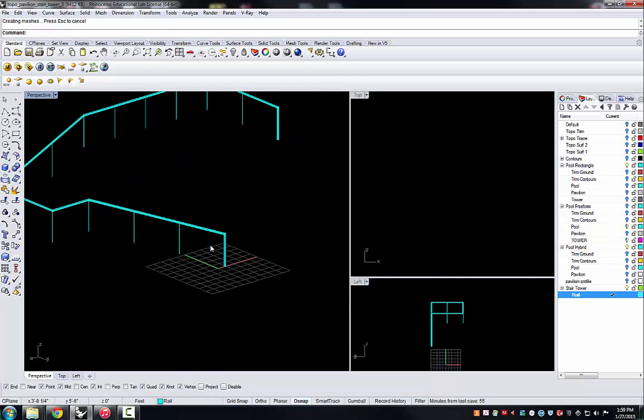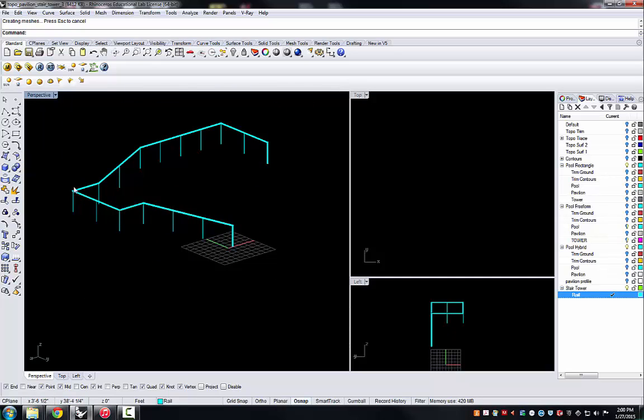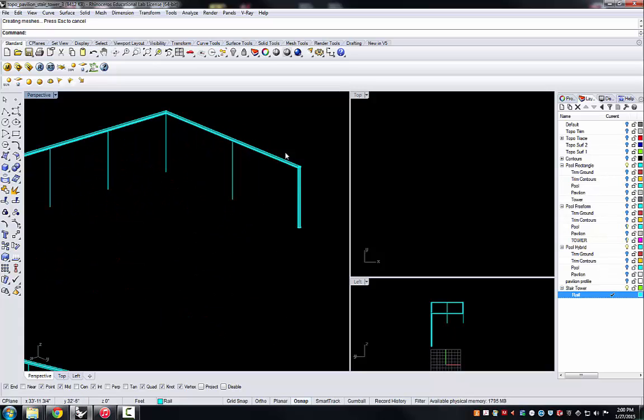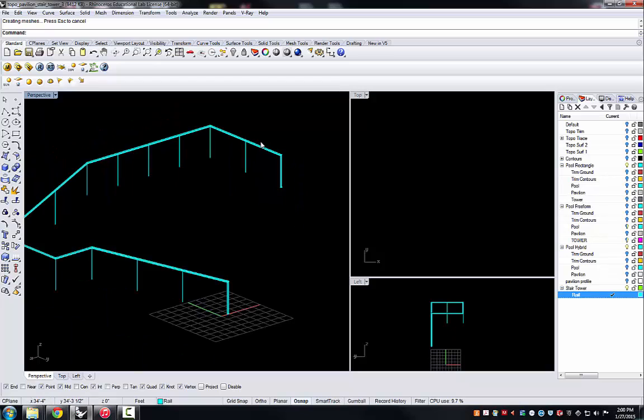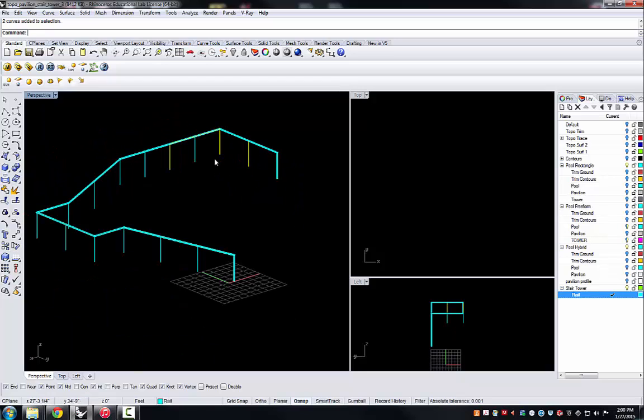And I have one pipe that creates the main outline of this. I can now select the other pieces of the wireframe and similarly pipe those to make the other verticals. So I'm piping again for a 1 inch radius.